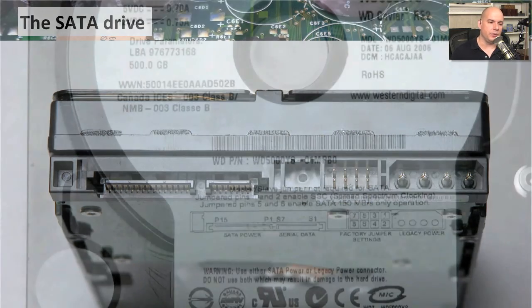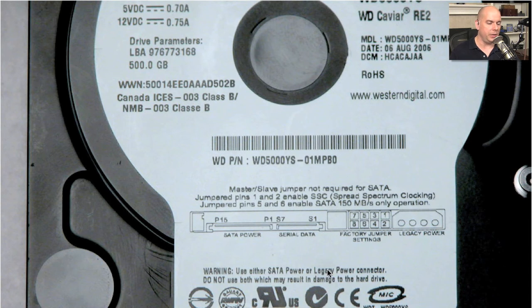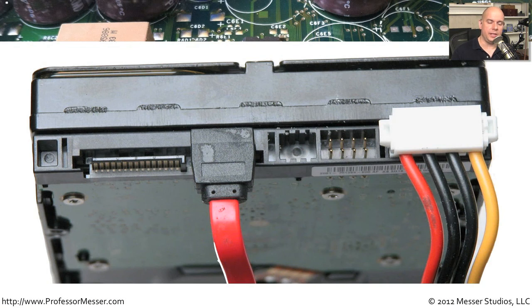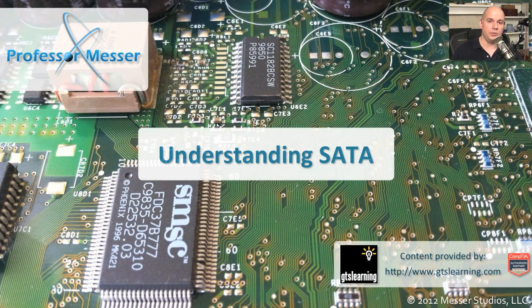If we were to look at the top of the drive itself, it would give us that documentation of what we just saw with the power on one side, our serial connection, which is the data connection to our motherboard, the jumpers that are on the side, and there's a legacy power connection built in right into the documentation on the top of the drive. If your power supply had some of the newer SATA connections, you would simply plug the power connection into the SATA power and you would plug your data cable into the SATA connector on the drive. If you have an older power supply, then you would plug it in very much like this picture shows, where you still have the same data connection, but you would use this legacy Molex power connector to make sure the drive was operational.